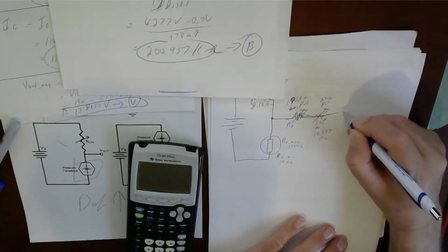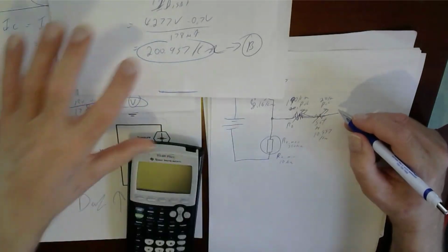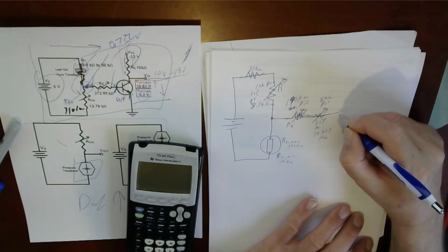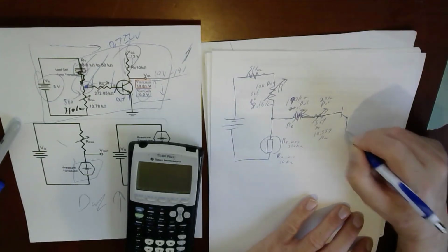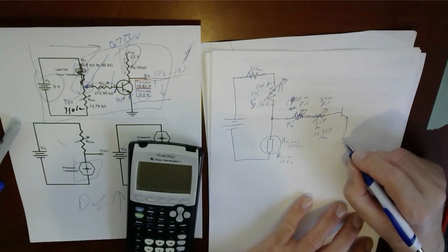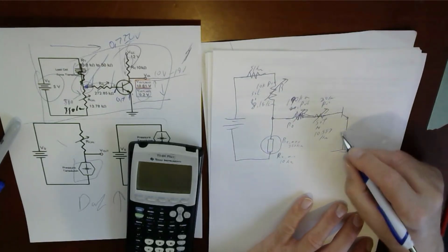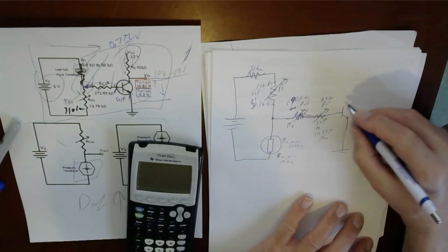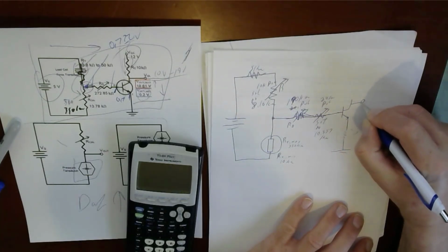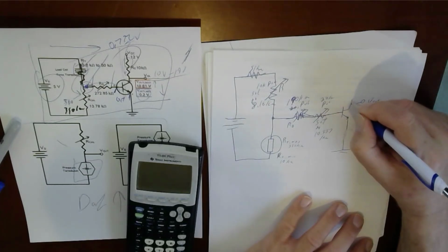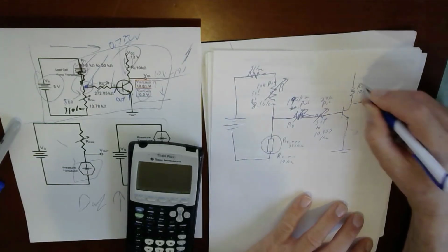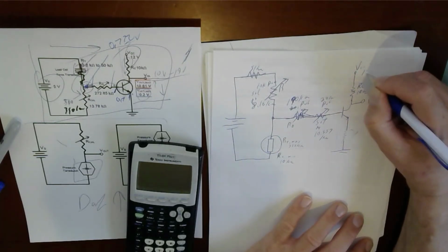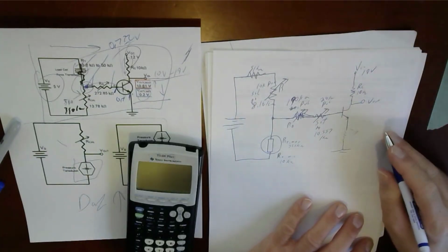So now I want to continue drawing my circuit so that it's doing what it's supposed to do. I'm going to do this guy here, and this guy. Now, the calibration resistor here, I'm going to think about the calibration resistor. Okay, good. Now, this is going to be my V out. This is my RC, and that's going to be 10 kilo ohms. And that's my VCC, which is 18 volts.